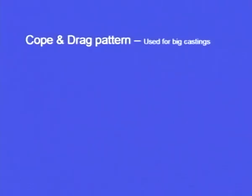Next one, cope and drag patterns. This is again used for making big castings. It is similar to the split pattern, but in the case of the split pattern, the cope half and the drag half of the patterns are compacted in the cope box and drag box respectively, and the gating system, that is the runner and the ingates, are molded in the drag box.